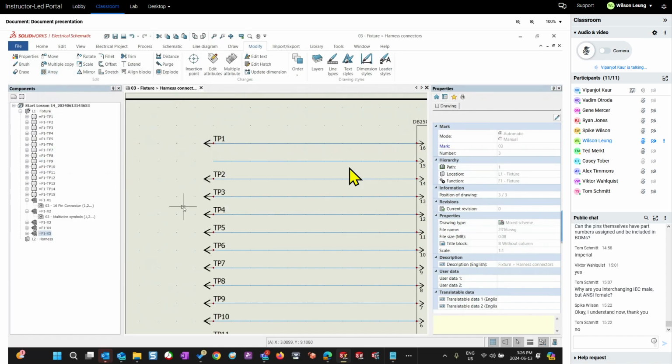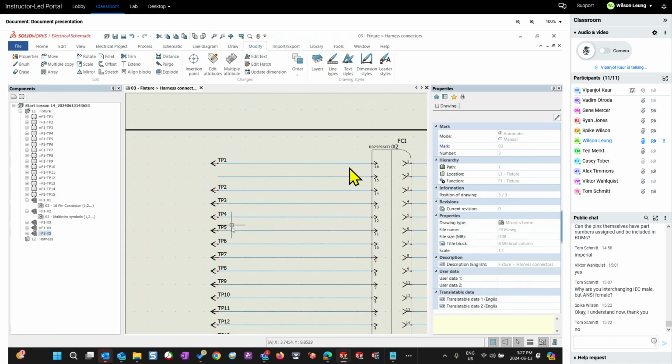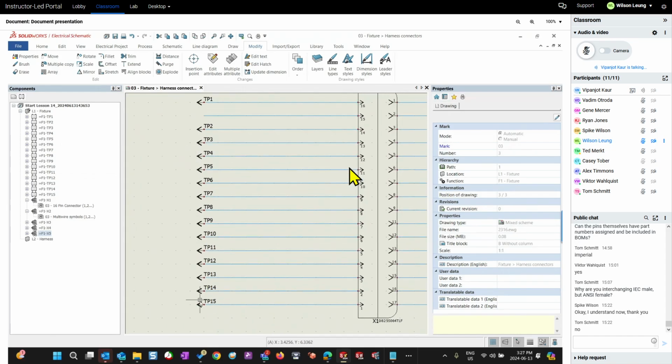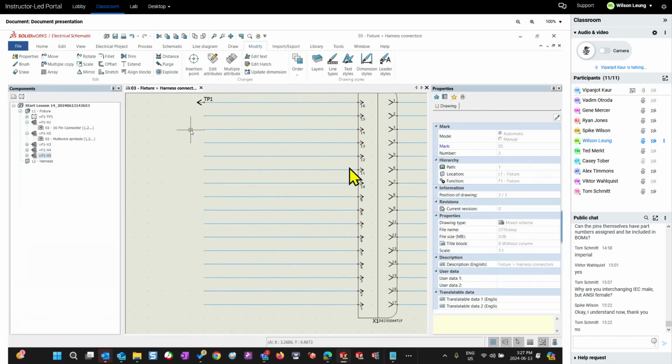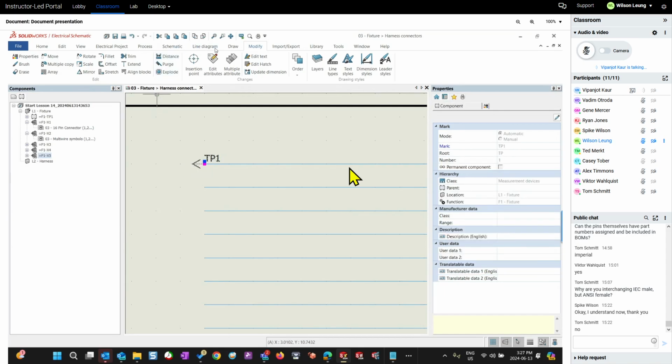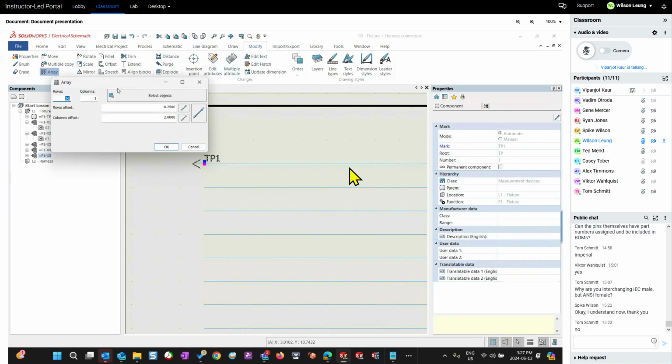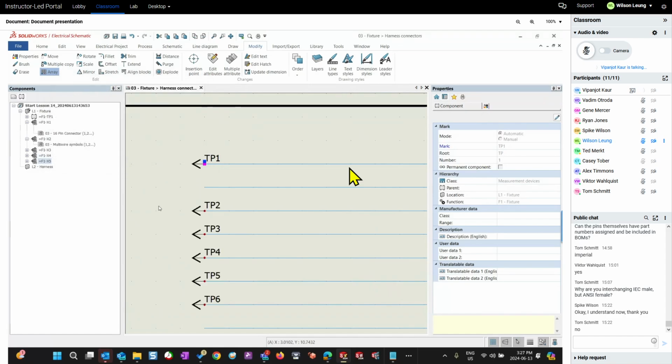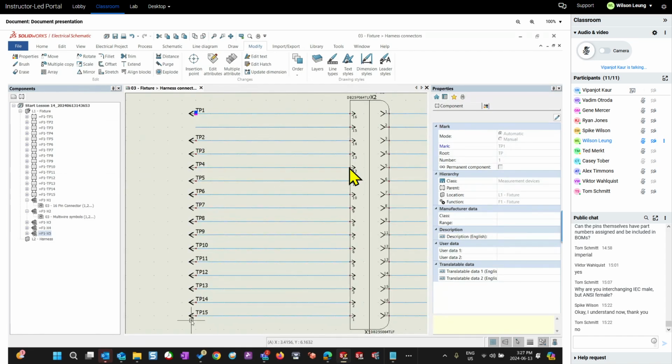But unfortunately, there's a glitch in 2024. It works the third time. It doesn't work the first 2 times. Something's wrong. So if I delete them all, instead of selecting, I'll pre-select it this time. Select it first. Now I can go to modify, array. My properties are set. Click OK. It did not work. It works the third time. I don't know why they messed it up.